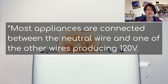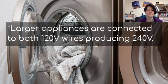Most appliances are connected between the neutral wire and one of the other wires producing 120 volts. So either the 120 positive or the 120 negative. So there's a 120 volt difference there. Larger appliances are connected to both the 120 volt wires, producing an overall 240 volts because the difference between positive 120 and negative 120 is 240 volts.